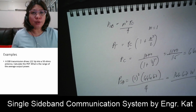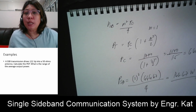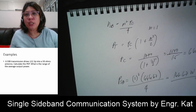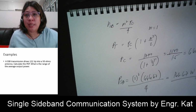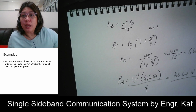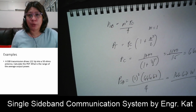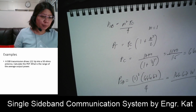Okay, so let's have another example here. It says a single sideband transmission drives 121 volts peak into a 50 ohm antenna. Calculate the PEP. So what is your PEP? PEP is your peak envelope power. And what is the range of the average output power?